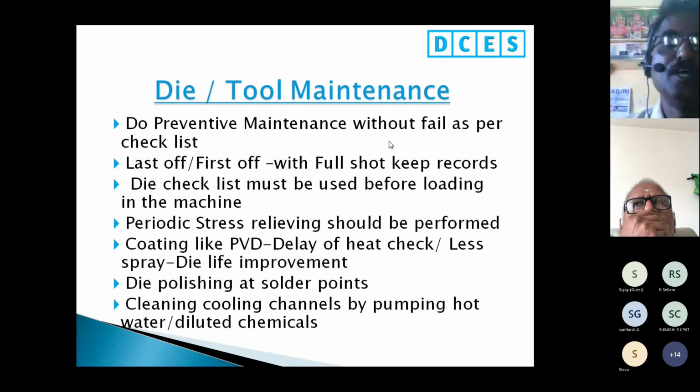Cleaning cooling channels by pumping hot water or diluted chemicals. We want to clean the die inserts, and normal water won't give a good result. Use hot water with the pump.